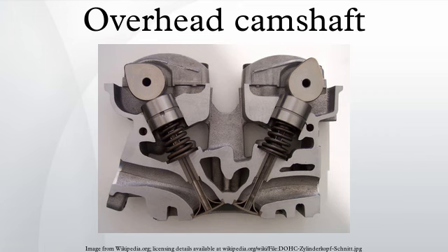Some manufacturers use a SOHC in a multi-valve design. Also, not all DOHC engines are multi-valve engines. DOHC cylinder heads existed before multi-valve cylinder heads appeared in the 1980s. Today, however, DOHC is sometimes confused with multi-valve heads, since almost all modern DOHC engines have between 3 and 5 valves per cylinder, but multi-valve and DOHC are separate distinctions.